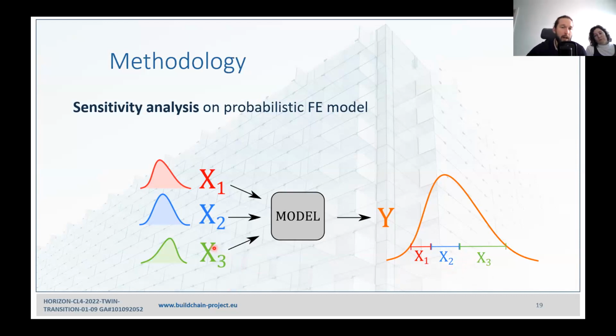And maybe parameter 3 would be the density of timber. What we could then do is take some samples of timber and measure the density, and we could fix the value of the input. But the problem in the building is that we cannot just take samples from the already existing building. This would be an intrusive method.